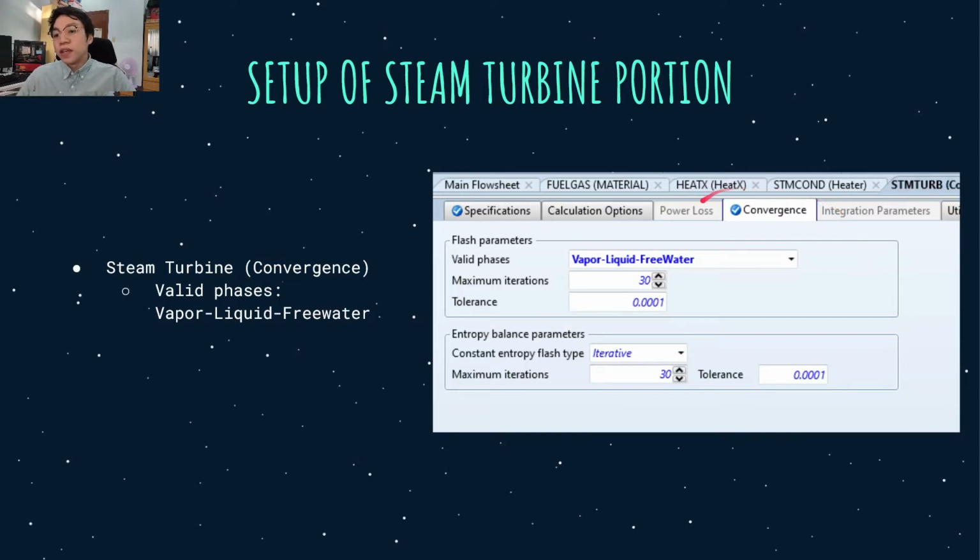So, as we see the steam turbine block, we're going to go to the convergence tab. On the convergence tab, we're going to specify that the valid phase is vapor liquid free water. This is important because if we input the wrong valid phases, it's going to create errors in our Aspen simulation.